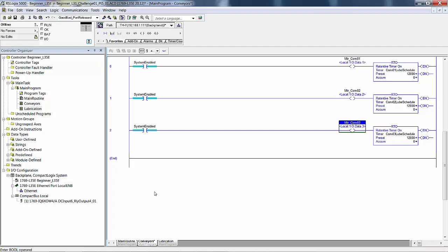Once the conveyor is full, the last carton is pulled on there, the next one that arrives should turn on conveyor 1 and conveyor 2. That way the new arrival gets pulled on to the entrance of conveyor 1. The first one that was on conveyor 1 is now the first one on conveyor 2, and so on. And then we would do the same thing with conveyor 3 when parts are called for.